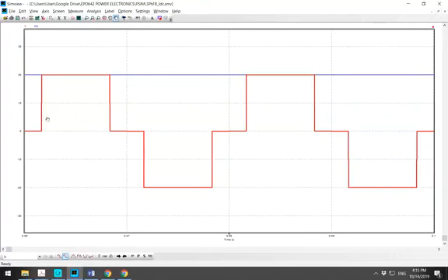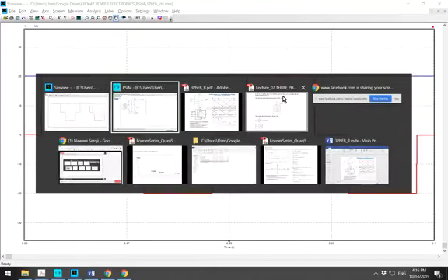So we're going to look at the Fourier series of the quasi-square waveform, so that we can obtain the harmonic content, so that we'll be able to calculate the RMS of the fundamental component, because the THD requires the RMS of the fundamental component and also the RMS of the total current. Okay, so let's look at this note.